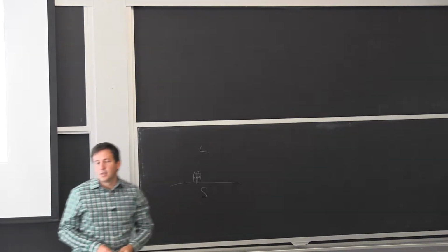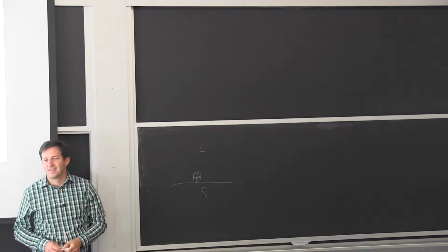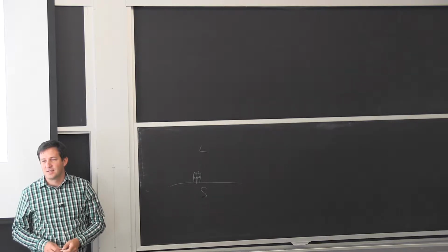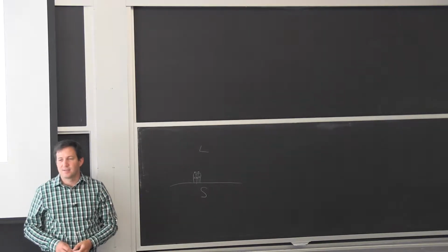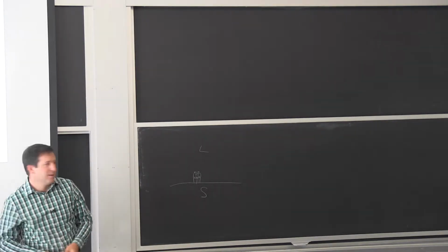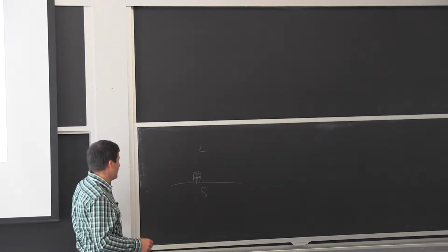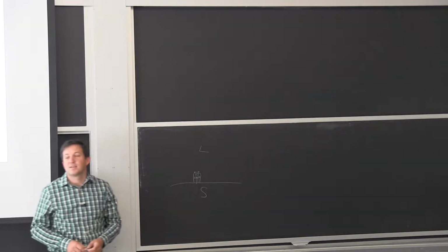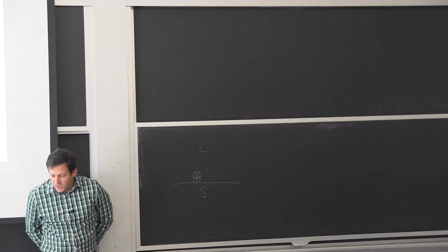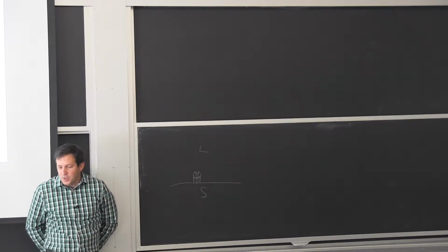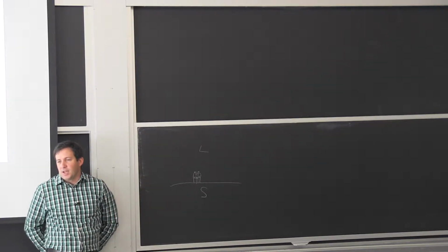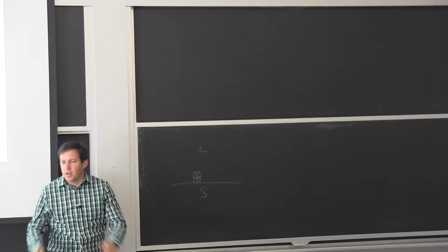Forgive me if I get the terminology wrong. This lamellar structure, is that what that is? Between the two phases? Yes. The lamellar structure, does that mean though that you just have very long and deep grains, or do you actually get the nucleation of new grains on them? The microstructure can even be called needle type eutectic, because each layer is very thin.